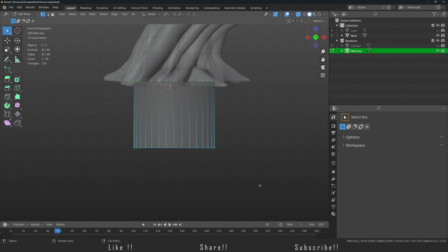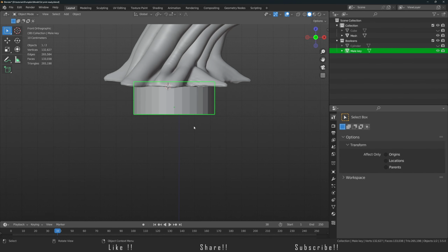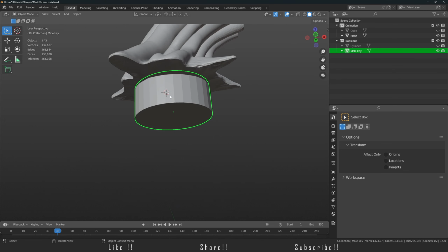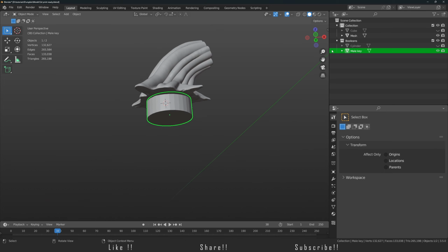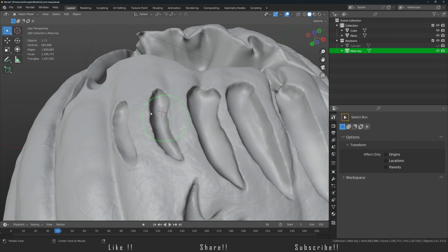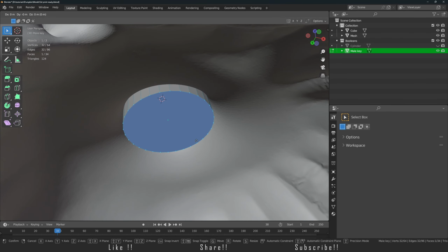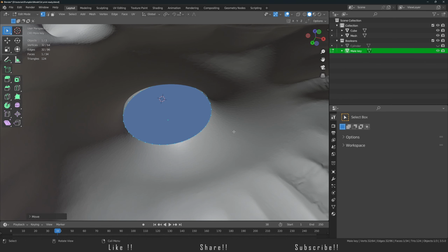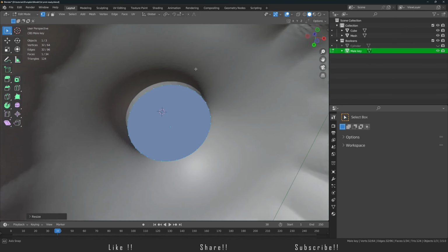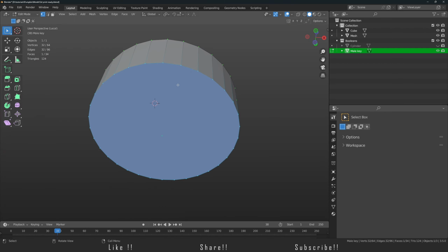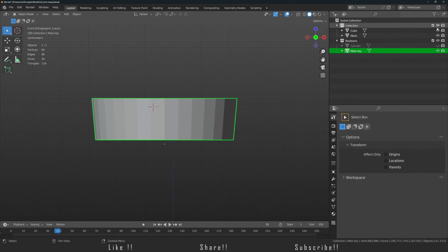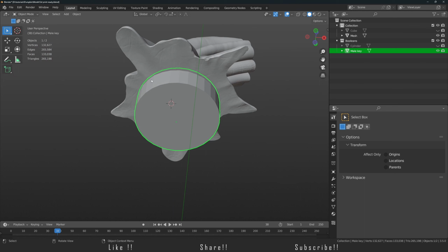And I am also going to select the bottom area, and I'm going to push up. The reason that I'm pushing up is I don't want this part to show up in the pumpkin through the eyes. So that's what I'm doing. So I'm just going to unhide this, and I'm going to push it up like this, and then I'm going to scale it down like this. So we basically have created the taper, and now we can actually use this to create the key.